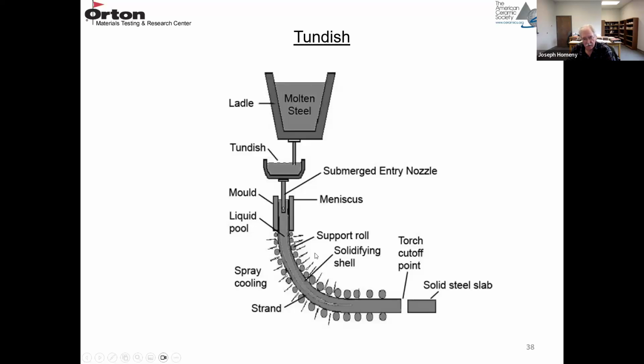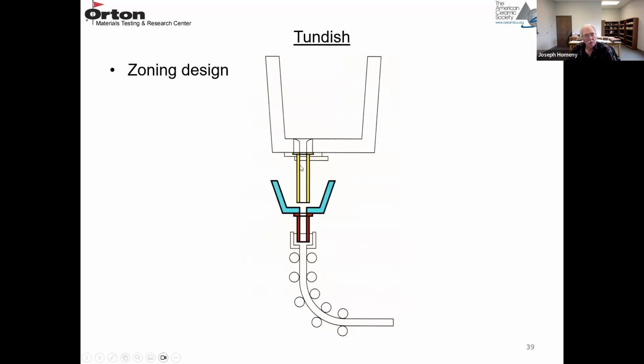So that's the arrangement. So here's your tundish. Here's your tube from the ladle controlling the flow of steel. Here's your tundish. And then here's another slide gate. There's a slide gate here. And here's another tube going into the continuous caster.